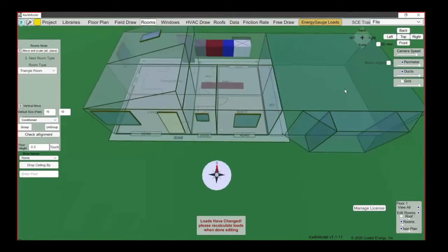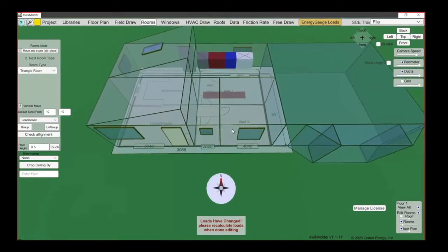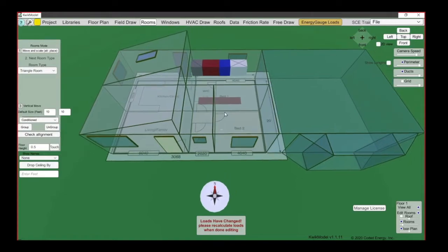And so it's very important that you know the direction that the house is facing and you have your north arrow pointed accordingly. And if we have time, I can do a load calc, and then I can come back and move this north arrow. So now these windows all face west, redo the load calc, and you'll see there's a pretty substantial difference, okay?